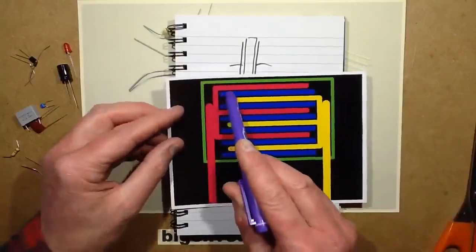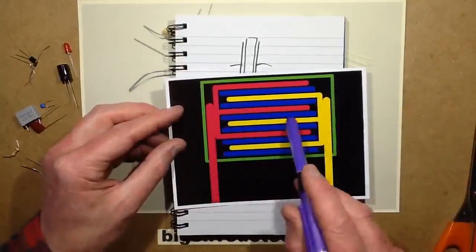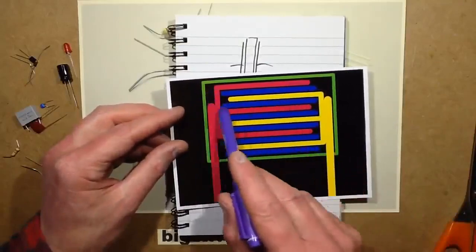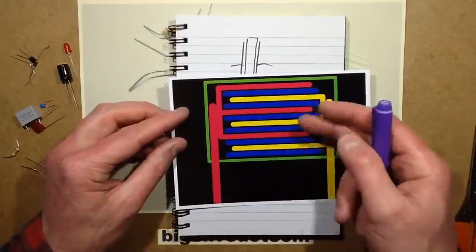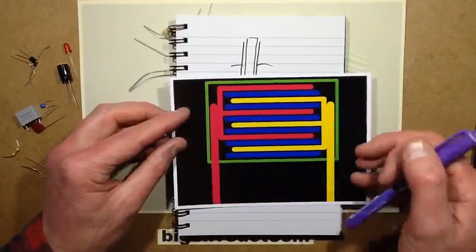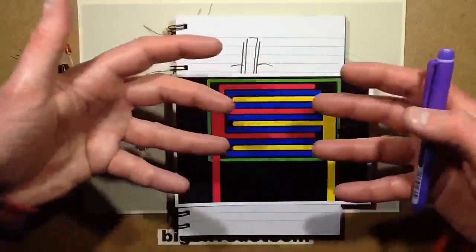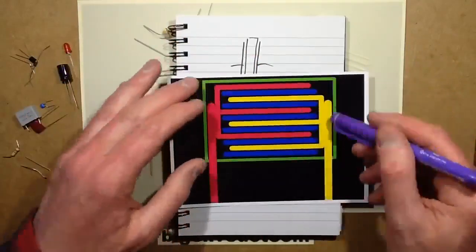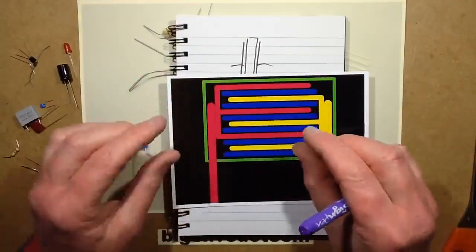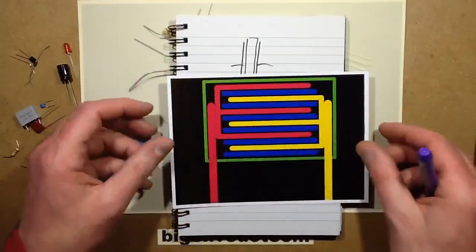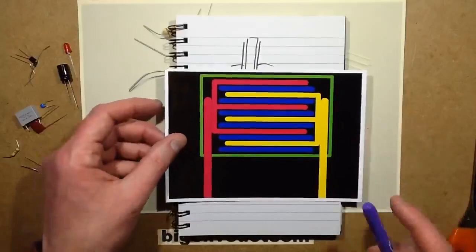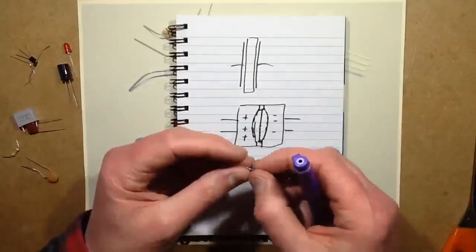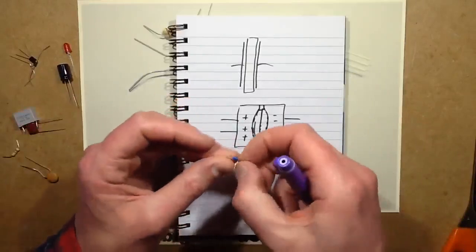And if you can imagine that the blue is layers of insulation in the ceramic capacitors, and these are metallized plates, then by alternating the poles, creating a sort of comb of them with insulators, and then putting a metallization down the end to connect them all together, you can create quite a large capacitance in a small area just by making it a multi-story capacitor, so to speak. And the layers of insulation in these are still going to be super thin. You'd need a microscope probably to see all the layers.